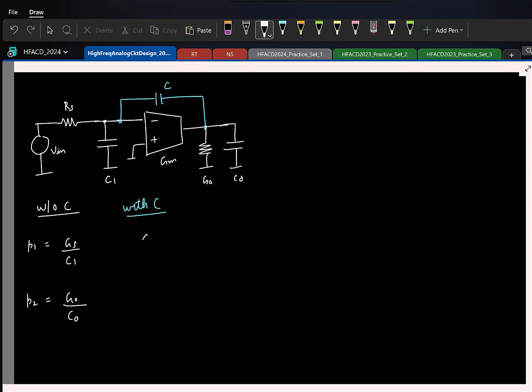The conductance is still the same, but as we saw, the act of putting this impedance across this amplifier can be reduced by using the Miller approximation. Again, if this was a voltage controlled voltage source wherein you know the gain from here to here, you could use it without error, but this is a current source, so we only approximately know the gain at low frequencies. So at low frequencies we do the approximation, and the total capacitance was C1 plus C into the gain and the conductance sources, right?